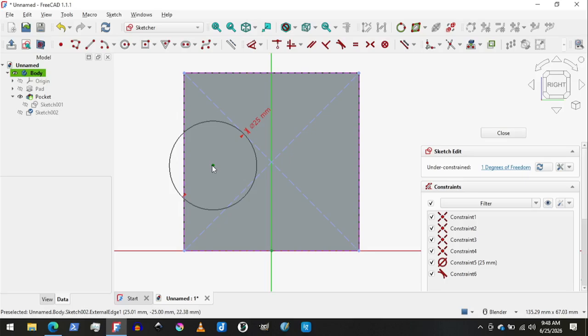Yes. So the basic geometry is there. It's the right size, but I need to go ahead and add these fillets. Now there's two ways that you'll see this done. There's fillets, which is a radius or a curve, and there's chamfers. A chamfer is like you just took a razor blade and sliced off the corner at an angle. Depending on what you're doing, you'll just choose what you need to use. In this case, we have to use a fillet, because that's what the drawing specifies. Okay? So I'm going to close the measure tool.